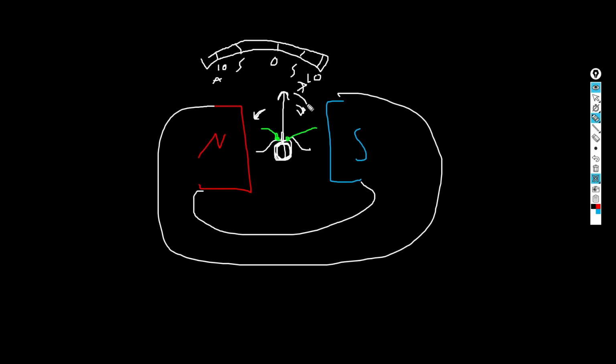So it would deviate because of a strong current. So it would move, and then the spring is trying to move it back, but the strong current, the electromagnetic force, has it stay here. When the electromagnetic force is gone, the spring would just point it back at 0. Okay, and if current comes from the opposite direction, the wire would point in the opposite direction.